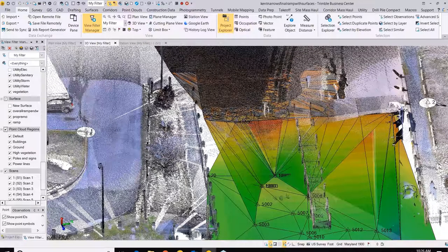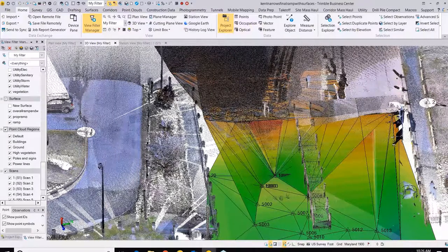and then number 2. These were set with 9-minute observations from NGS. NGS says that you take 1 shot, then you turn a third, and you turn another third. That way you close that. So that's how they were set. Also, I ran a traverse loop off of those to control that back down. So that was run off a controlled network from the VRS, yes.